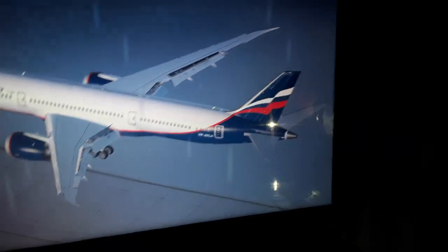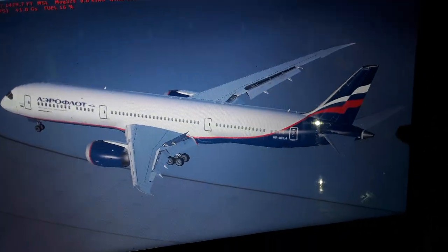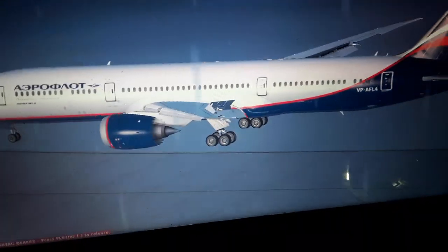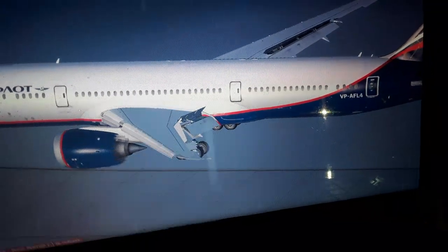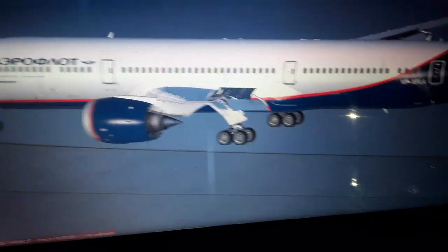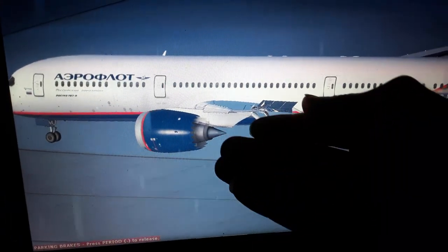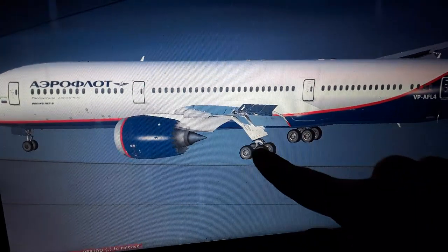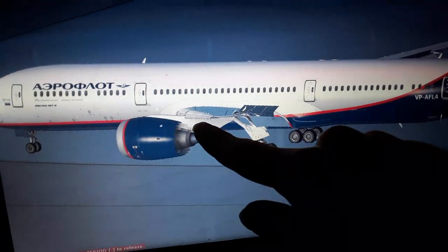So you can see the flight controls movement also as I move this. We can use also the elevator from the horizontal tail instead of using the whole stabilizer. You can see also the bottom surface of the wings. You can see they are more flat. So when we fly with an airspeed in flight, the airflow is moving slower below the wings because it's more flat, using Bernoulli's theory of fluids and Newton's physics.